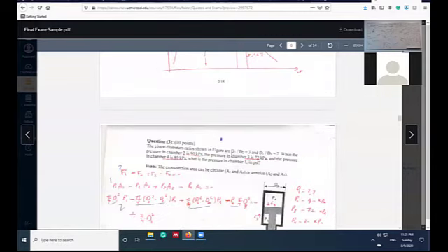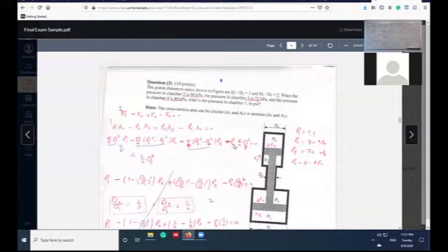So make sure that you know how to follow this. This problem is typical to problem number 2 or 3 in the midterm 1, but with a little bit more details. So I apply the force balance. This pressure is upward, this pressure downward, upward. It's always normal to the piston. So this is upward. F3 upward, F4 downward, F2 downward, F1 and F4 in the whole area, but 2 and